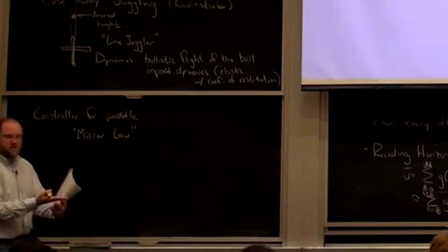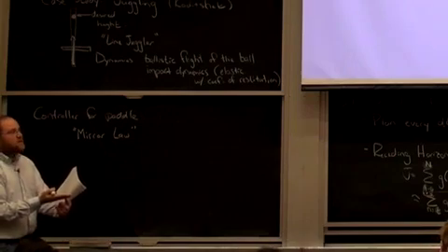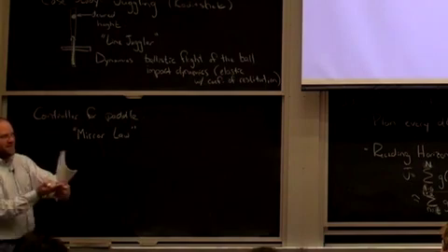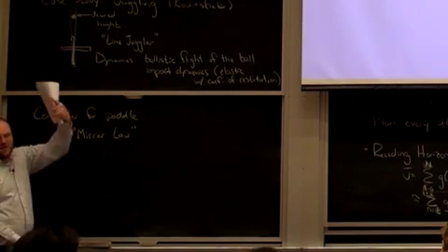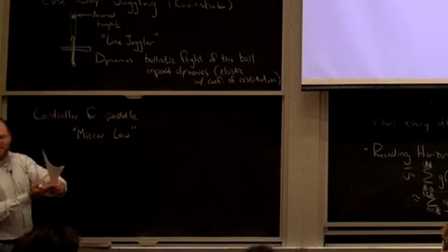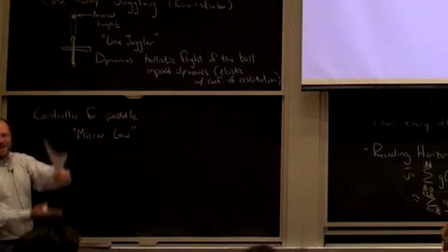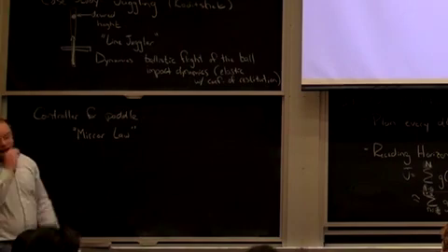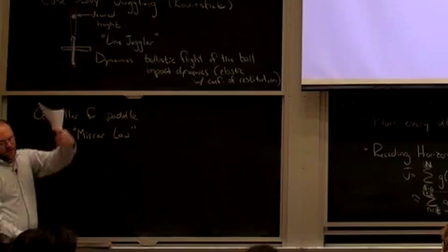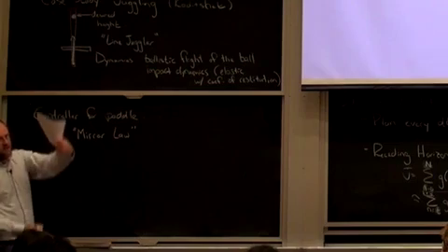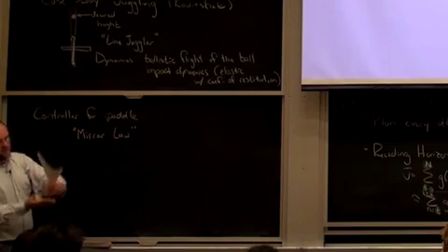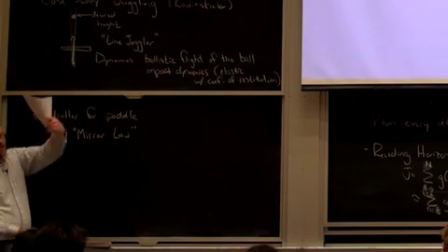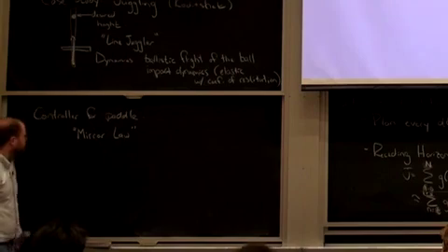Turns out if you can sense the state of the ball, and you just do a distorted mirror image of that ball, then everything gets really easy, right? Your impacts always happen at the same place, and just by changing the velocity here, you can roughly affect the impact height. So they can nominally stabilize some limit cycle with just mirroring the ball, and they add an extra term to stabilize the energy to get it to whatever height they want, right?